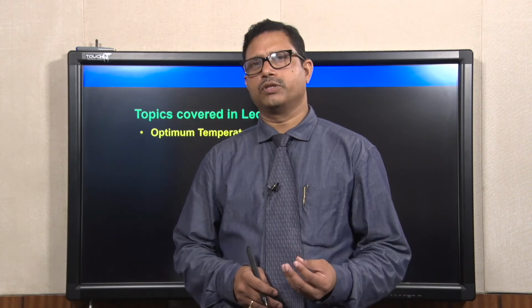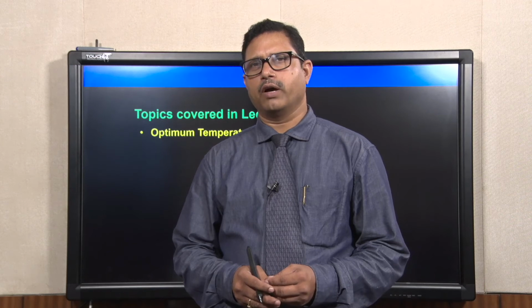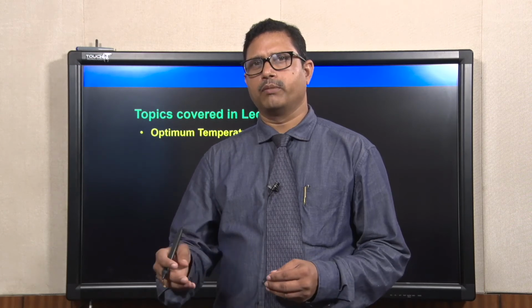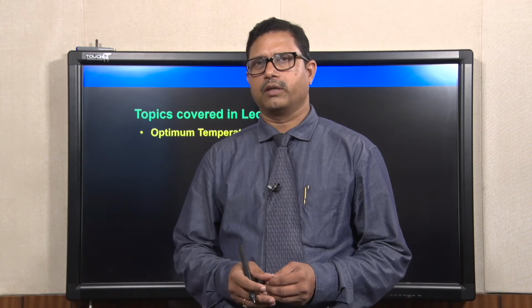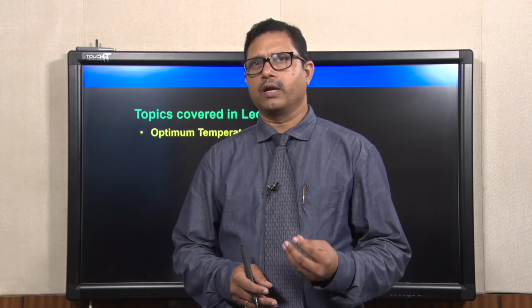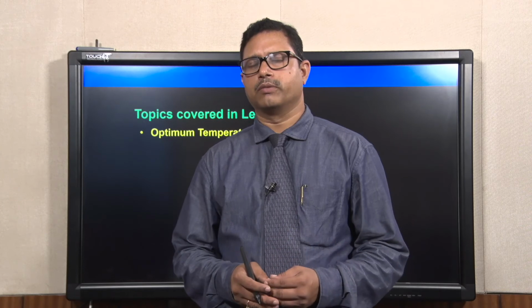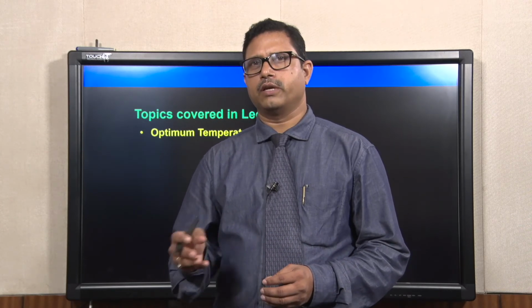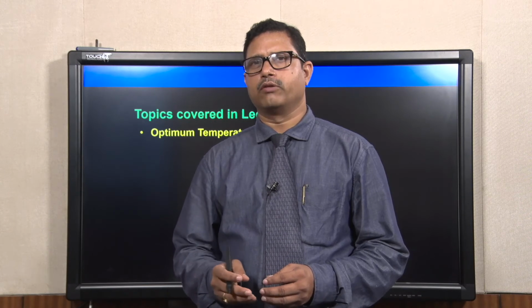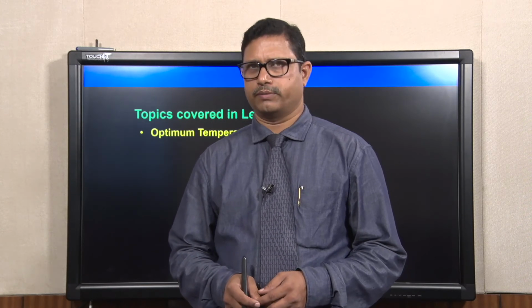The only case which we have considered where we can find the optimum temperature if we wanted to run at a single temperature, that is for single exothermic reversible reaction, where the change in temperature changes the equilibrium conversion.